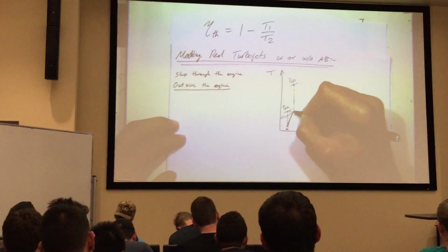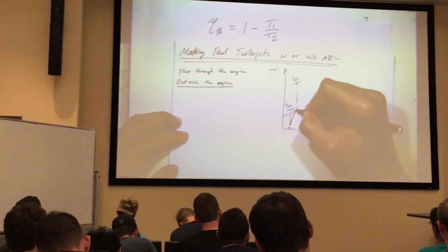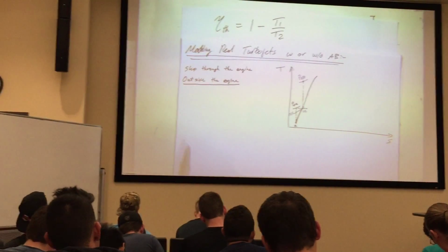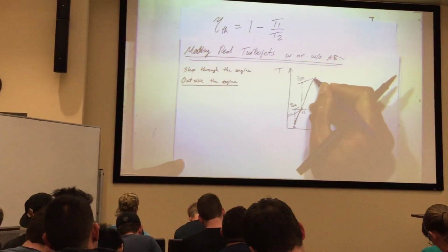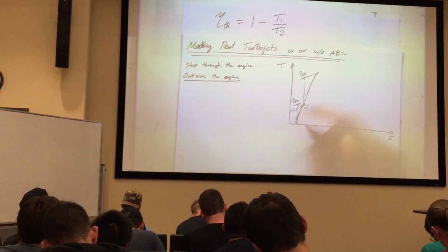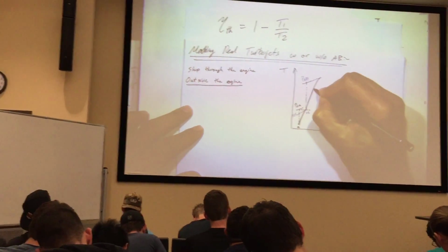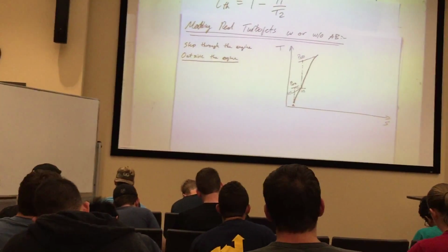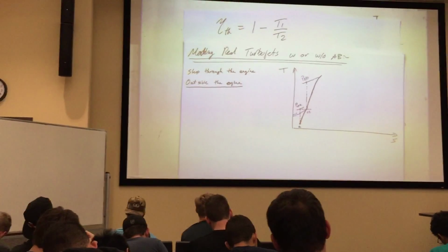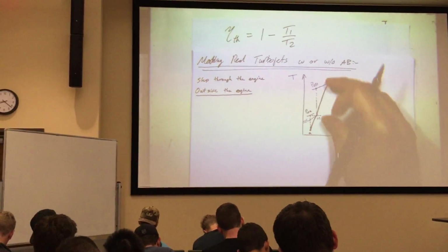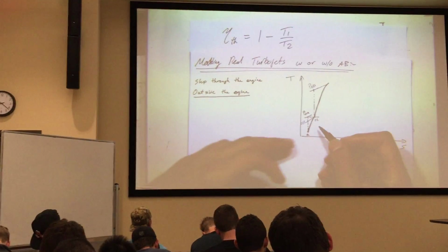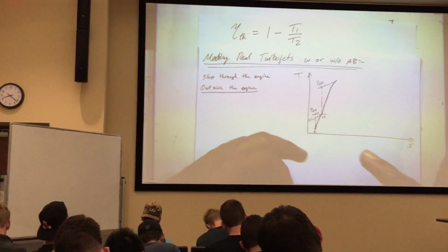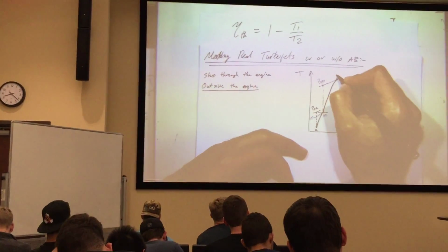My real situation is going to be along the same curve of PO3, just something like this, and we extend it all the way right here. So that's this curve. So it's almost the same as the inlet. Well, it makes sense because I'm actually applying a compression process, but just a larger delta P relative to the inlet diffuser situation.